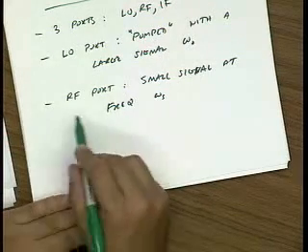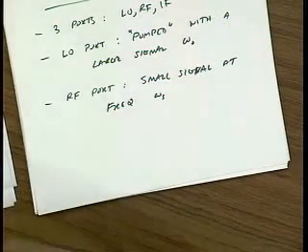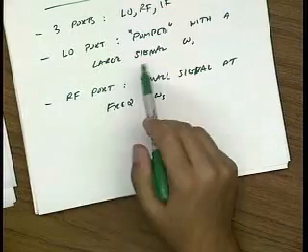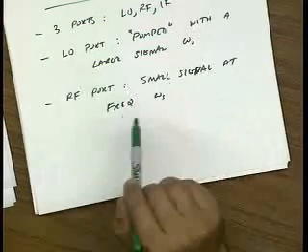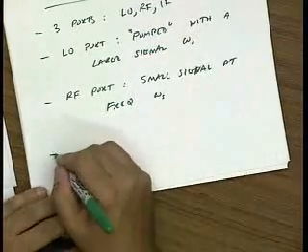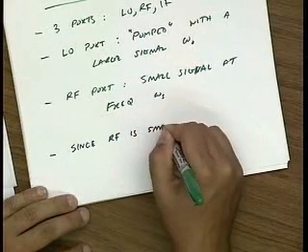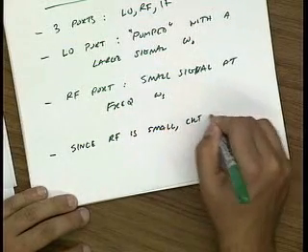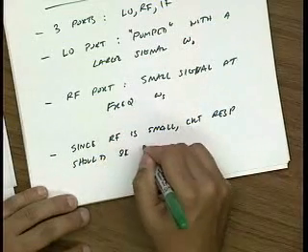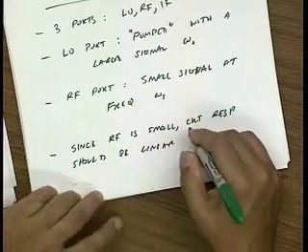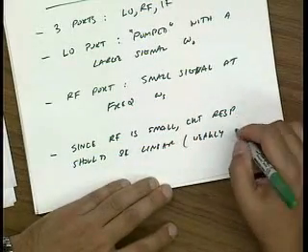So if the RF signal is relatively weak, the response of the circuit should be linear. But because it's being varied in a time-varying fashion, we would expect the response to be linear time-varying. So let me just write that down. The circuit response should be linear, or at best weakly nonlinear, so the Taylor series stuff we did should be valid.